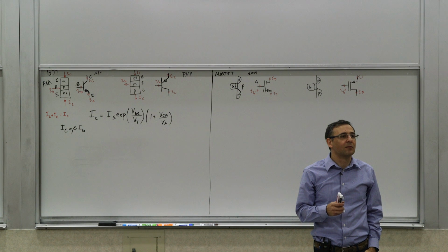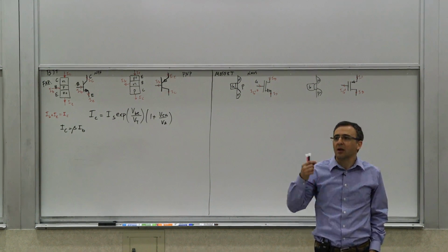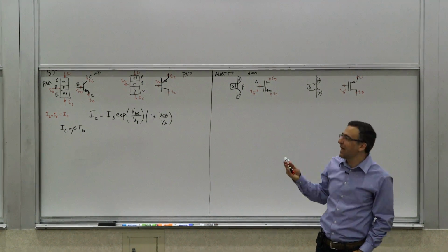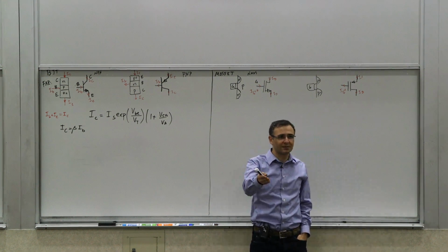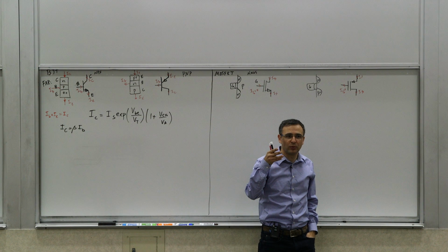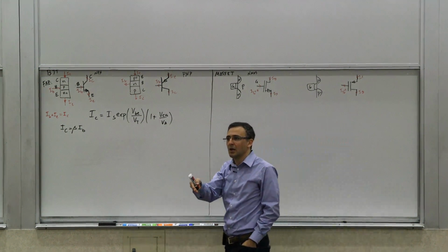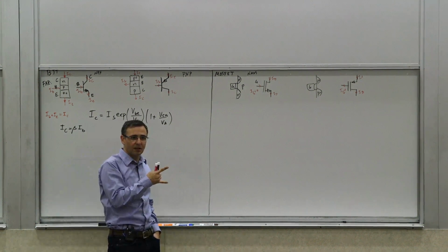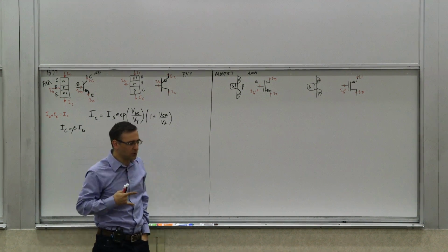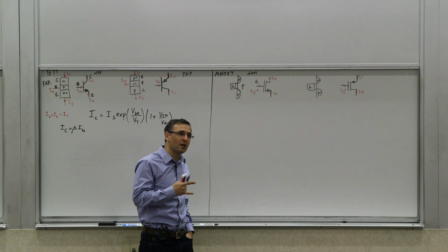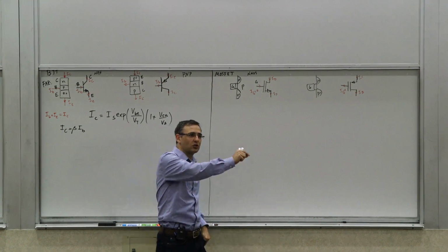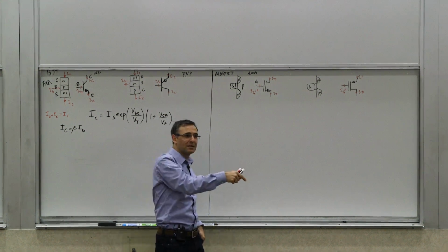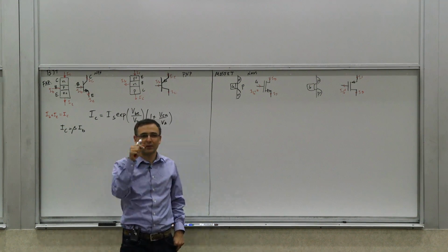More precisely, the way to think about it, and we'll see this is a recurring theme, is that whether something is current drive or voltage drive is a relative matter. What really matters is the impedances, the drive impedances, the level of the impedances, and what the driving point impedance is, the impedance of what you're driving. So if you are driving a high impedance, generally speaking, and we'll see this again in many different scenarios, you are driving a voltage. So it's a voltage sensor. It's something that measures the voltage. If you're driving a low impedance, it's easier to model it as a current sensor, something where you put the current in and you measure it.